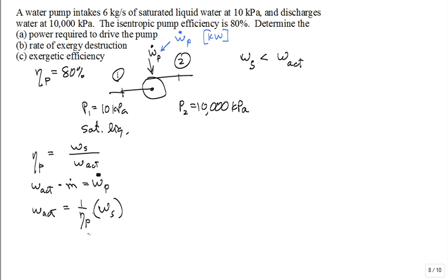It's at the end of Thermo 1. It's in Chapter 6, the last section of Chapter 6 in our textbook. It talks about the exact problem we have. And you get an equation that is something like the work, internally reversible, equal to negative integral V dP. Warm, fuzzy feeling? Does it resonate? And so if you're doing a pump, the specific volume of saturated liquid, and what's coming out of the pump?